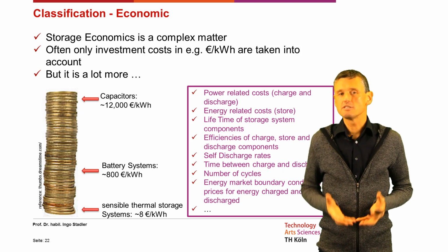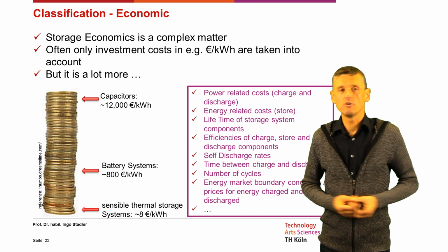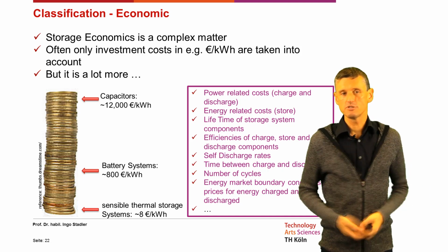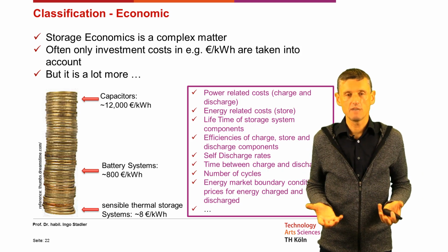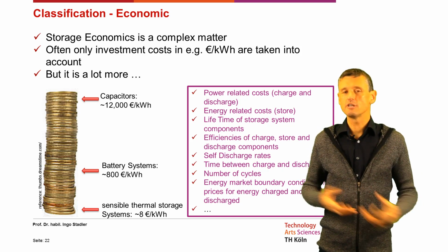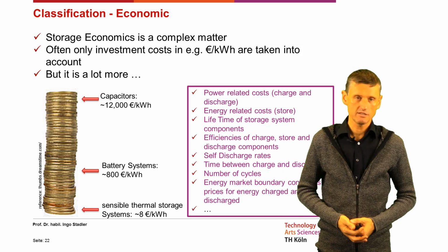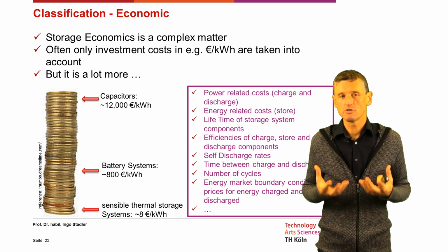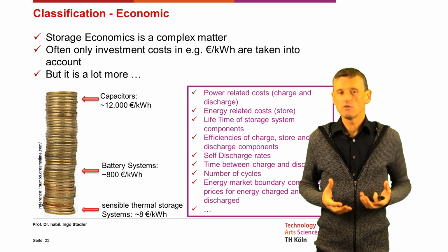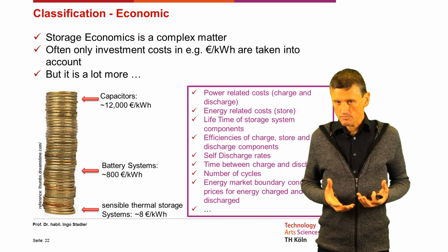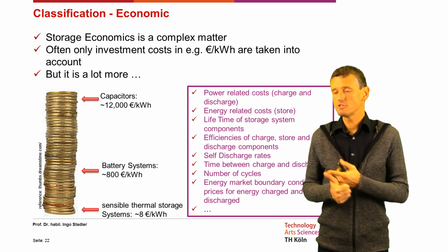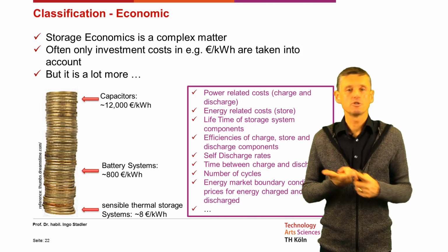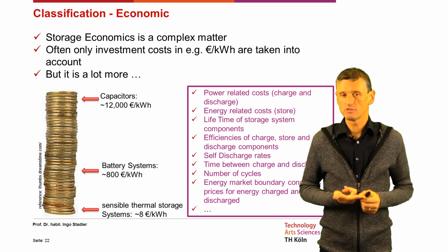Storage economics is a quite complex matter, and quite often, and that is completely leading to wrong conclusions, only the investment costs, for example in euro for a kilowatt hour of storage capacity, are taken into account. But to judge on the storage economy, we need to take also into consideration not only the energy related costs, but also the power related costs play a big role. So the charge and discharge components of a storage.